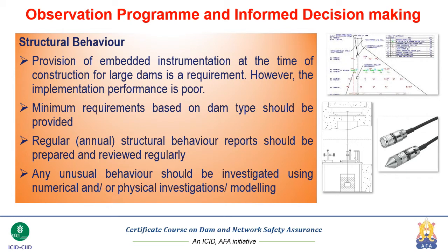Structural behavior of the dam is another place where the observation program has to be there for all dams. The provision of embedded instrumentation at the time of construction for large dams is a requirement. However, in our country, we have a difficulty in maintaining a very safe and sound instrumentation system in many of our major dams. The instrumentation systems go out of order very quickly, or they are not implemented properly, and the structural behavior as reflected by them is not available for the safety evaluation.